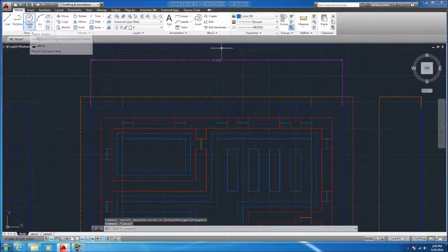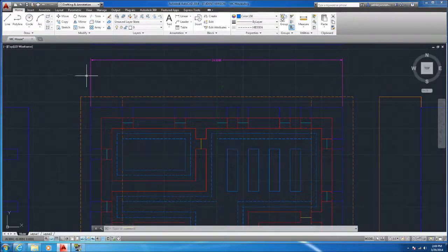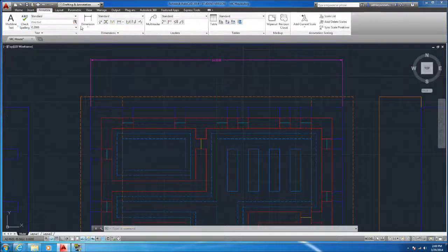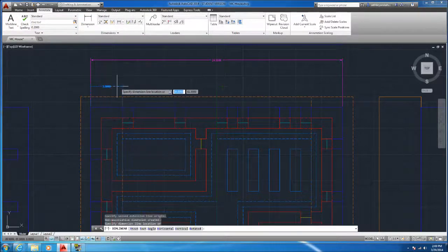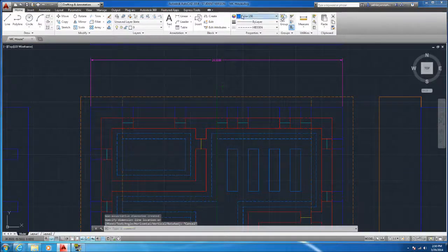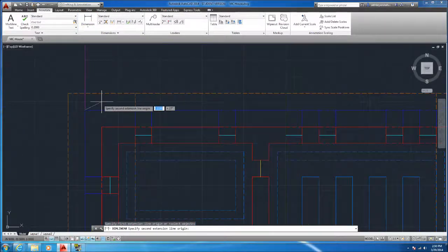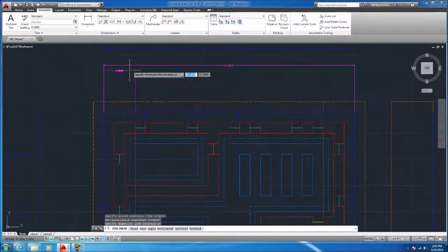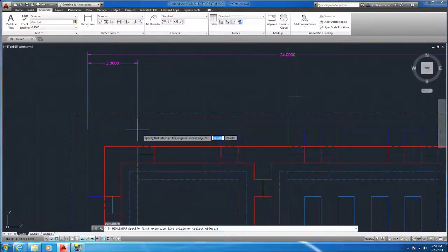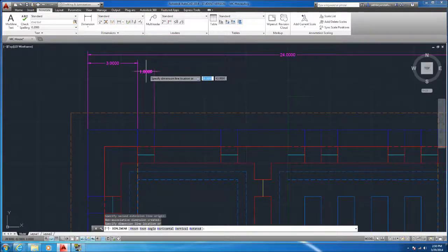Now, if you want to do this the way the architects do it, or how you're supposed to do it in professional drawings, you start like this. Then if you go to annotate, go to dimension. Since technically we're working with blocks, the only really accurate measurements we can do is with masonry. And pretty much the way masonry works is you're going to annotate and you're going to dimension from masonry openings. So from this opening to this opening, and then from this opening to this opening.